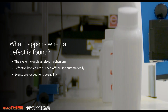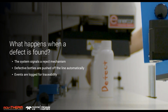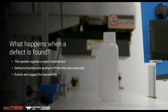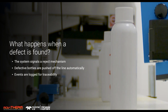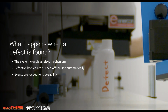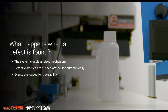Once we find out that it's a failure, we can do a number of things. One is we have digital I/O that we can send an output to, so we can send it directly to a rejector. A lot of the time that's time-based. So if you have a conveyor that's running at a consistent speed, you may be able to just say, okay, let's reject it half a second later, and it will send a signal to the rejector and it will reject it.